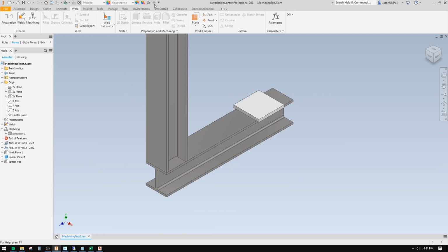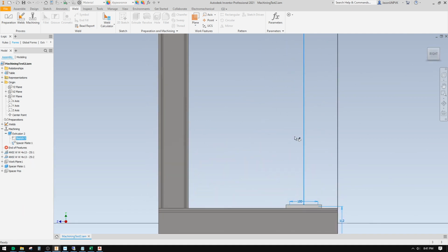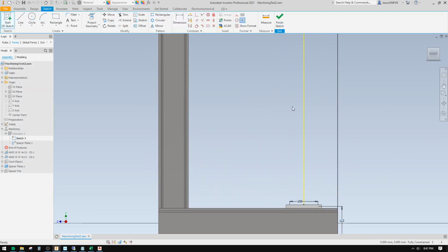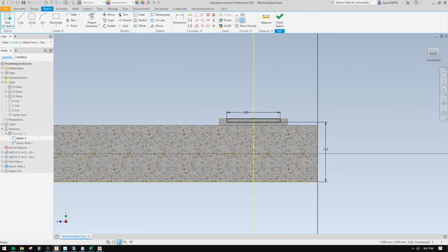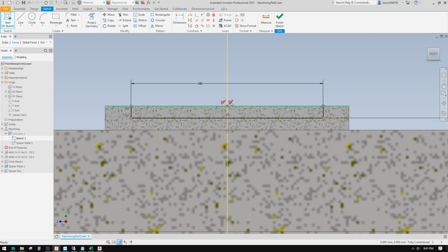Now, if it does, sometimes this little design doctor will come on and it'll give you problems. If that does happen, let's see here. I'm going to unsuppress that. You have to get a little more creative with your sketch. Like, for instance, F7. Well, let me press F8 and I'll get rid of this constraint. Having a hard time seeing my keyboard here.